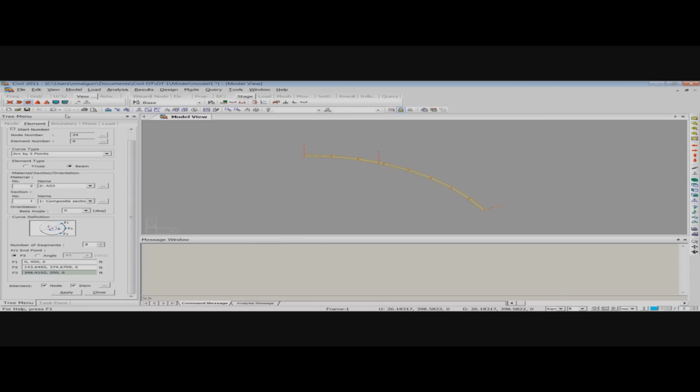In the finite element analysis, the finer the element is, the better the results are. So for that, I'm going to model this curved element into 40 different segments, and I'll again select the different nodes, and as you can see here, in this way the element has been modeled in 40 different elements. Similarly, I will do the same thing for other nodes, and as you can see here, I'm modeling the full width of the bridge.